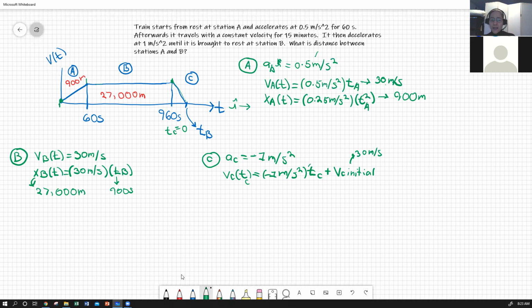So we can look at any time within this region C where we're going to say t equals 0 when we first put on the brakes, we've got a negative sign. So this first term's negative. The second term is constant. So our velocity is decreasing with time, which is what you expect when you're decelerating. So that's kind of a little check that, hey, did I get my initial velocity right?